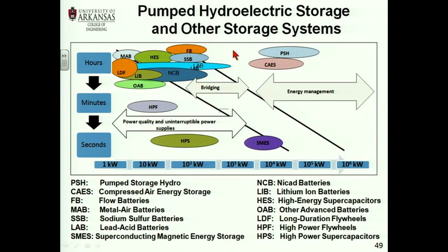And so the flow, the best one in terms of the return efficiency is the lithium ion. You are about 95%. The flow battery is about 80%, 85%. So that's the reason. But the advantage of the flow battery is that power and energy are not related. You can increase the energy capability of the flow battery and still have the same power capability.